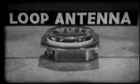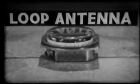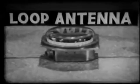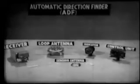The direction-finding antenna affords a big advantage. It enables us to use radio stations that transmit a non-directional signal, provided, of course, they transmit on a frequency within the range of this equipment. There are several types of stations we can use with the ADF. Non-directional beacons called homers, low-frequency radio ranges, portable non-directional beacons, and commercial broadcasting stations.